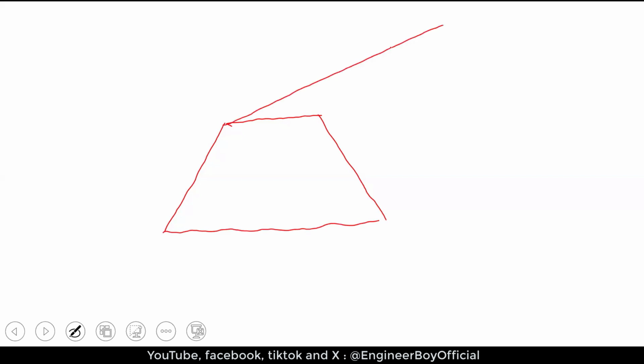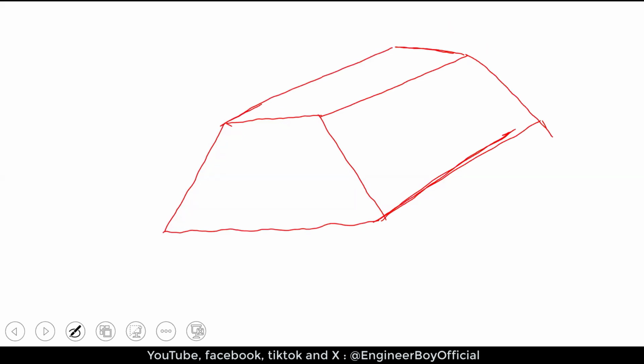And one another thing that should be given in order to determine the earthwork, let me just say if I have the same embankment like this one, is the dimensions related to the section. We should have the depth for both ends and the formation width, which should be this portion, and this is B. Now side slopes should be known, like side slope S1 on one side, and for the other side, let's say this is S2.